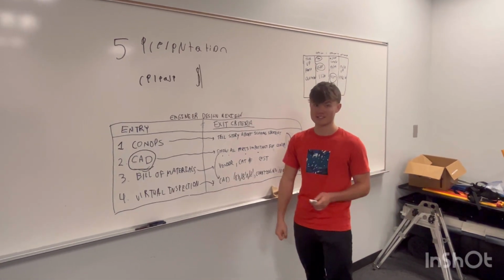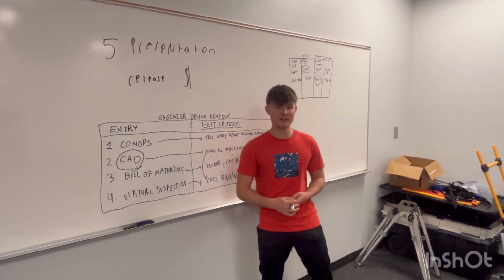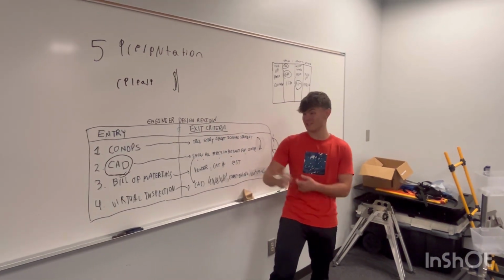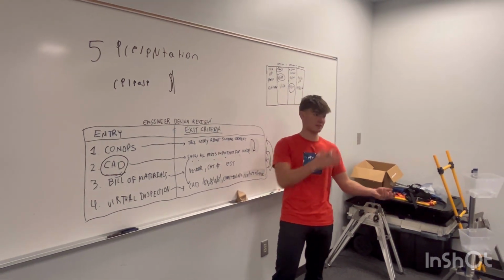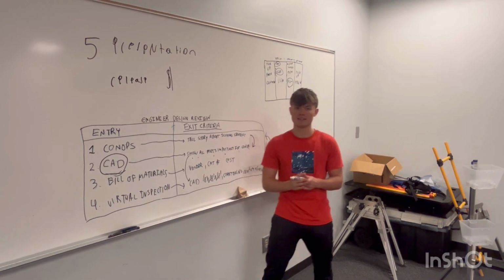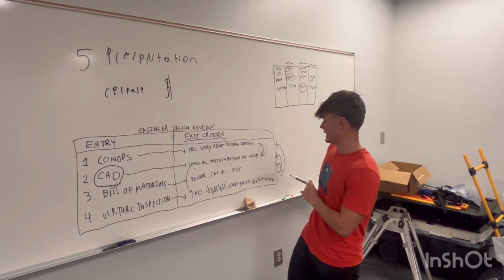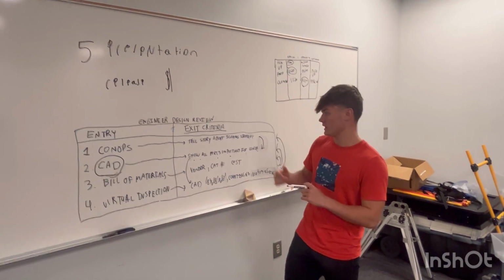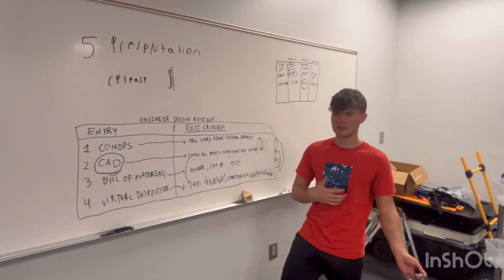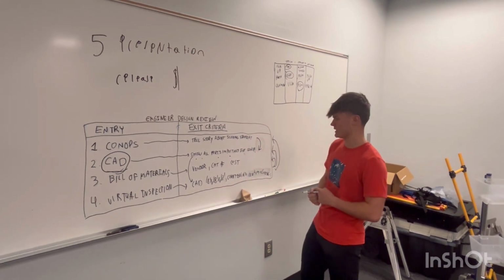You do the virtual inspection in the CAD, and the bill of materials comes from the CAD, because if you get the STL files from GoBuilder, you know the exact files you're getting and how many of them. It's all detailed in SolidWorks, or if it's another software, I'd assume the same kind of thing. It tells you the maker and the part number, all in your CAD automatically, so you don't have to research anything and bring it up.